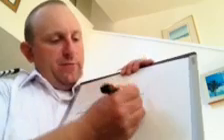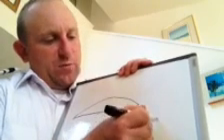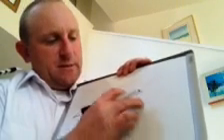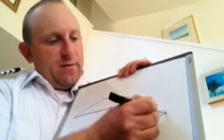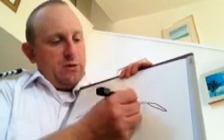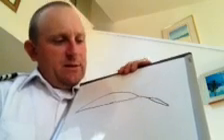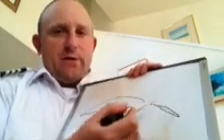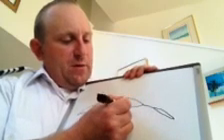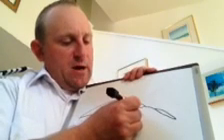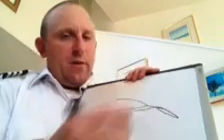Okay. The flap is on a track. So rather than just being a normal slotted flap like this, this flap has a track that extends the surface area out here, like that. So what that does is increase the surface area. It gives us the most amount of available lift.